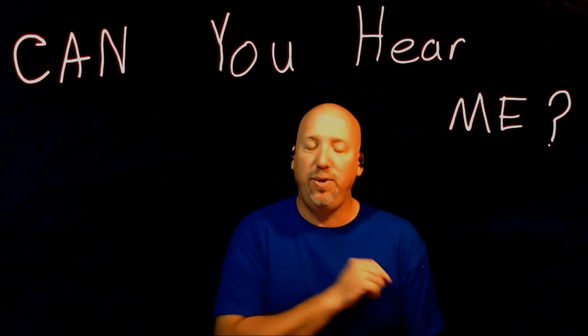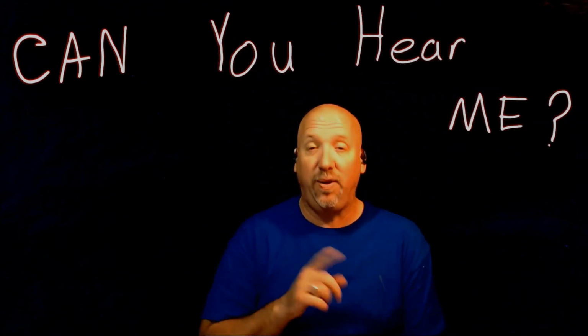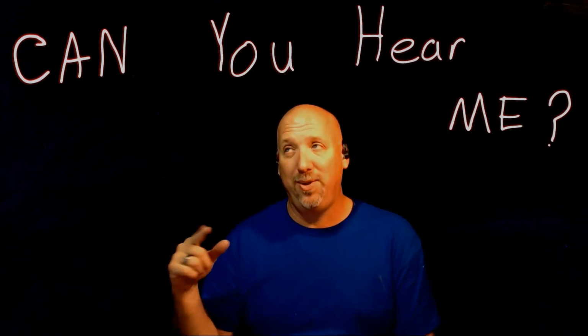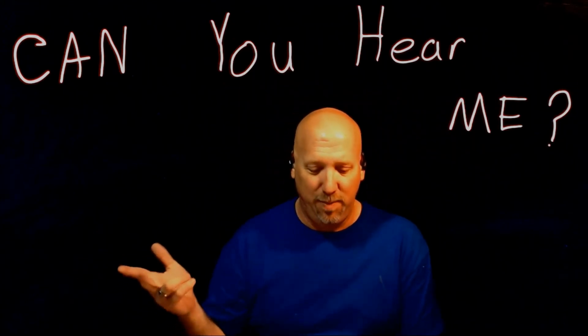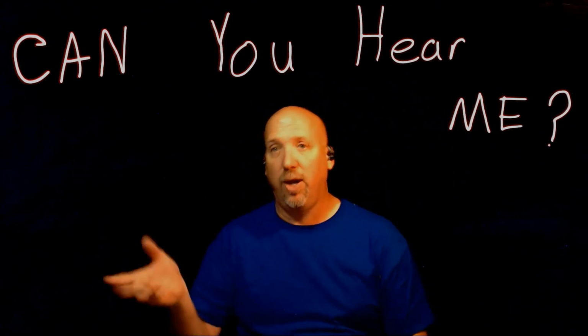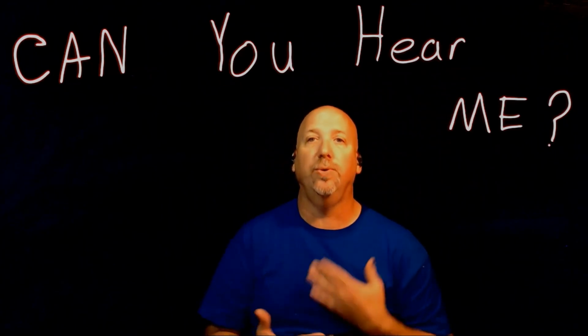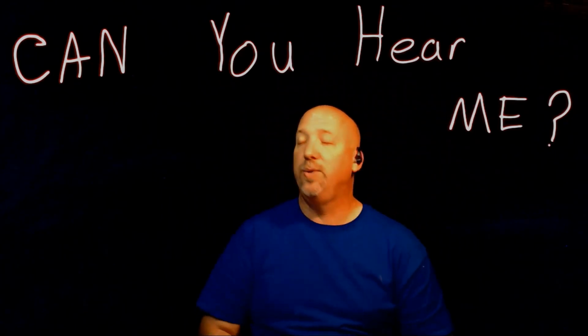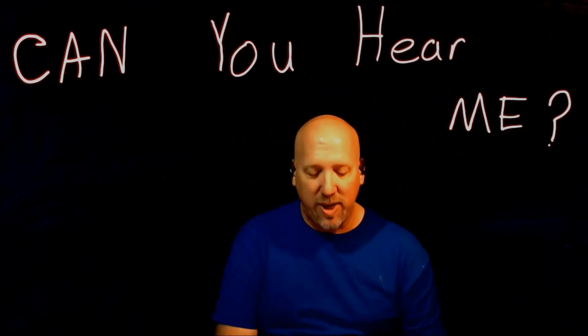Each manufacturer uses different terminology, which also varies by scan tool manufacturer, such as Diagnostic Circuit Health Check, Class 2, GMLAN, DCC Check, All System Scan, All Codes, Health Check, etc. It's all doing the same thing. Know your tool, know the system you're working with there. So whatever it's called, use it whenever it's possible to see what's going on in the entire vehicle.